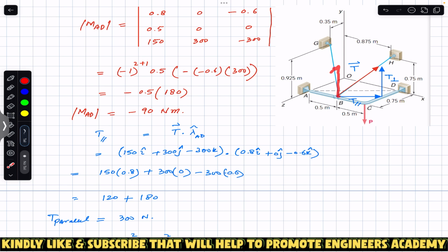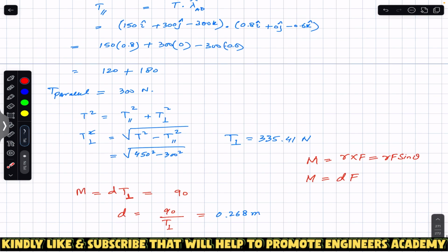Once we find this perpendicular component, as you can see, we can draw this T perpendicular here as well, and we can draw that T parallel here as well. This T perpendicular is going to produce the moment about that AD, and if we multiply it with that distance, that will give us the perpendicular distance between this BH and AD according to the scalar definition of the moment.